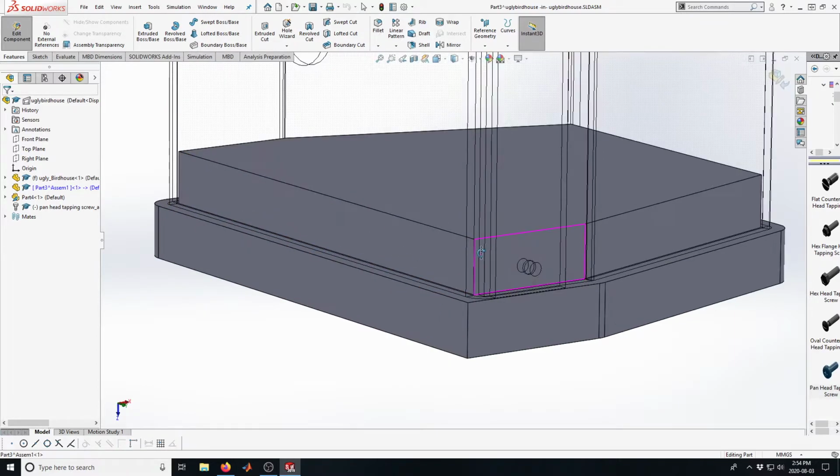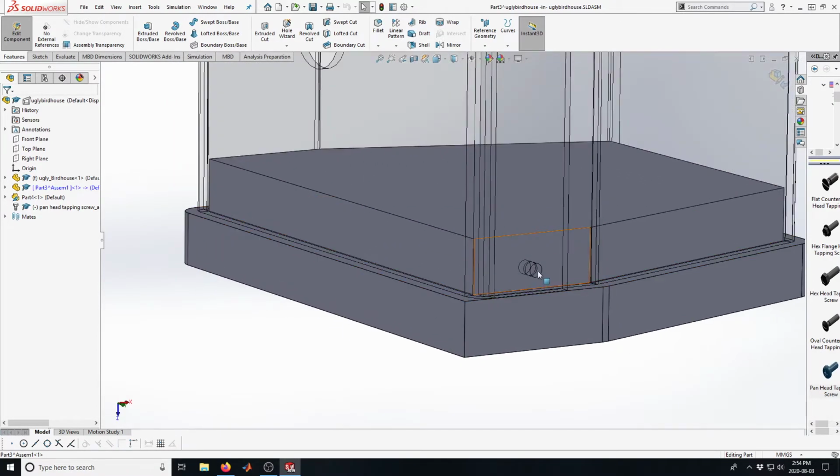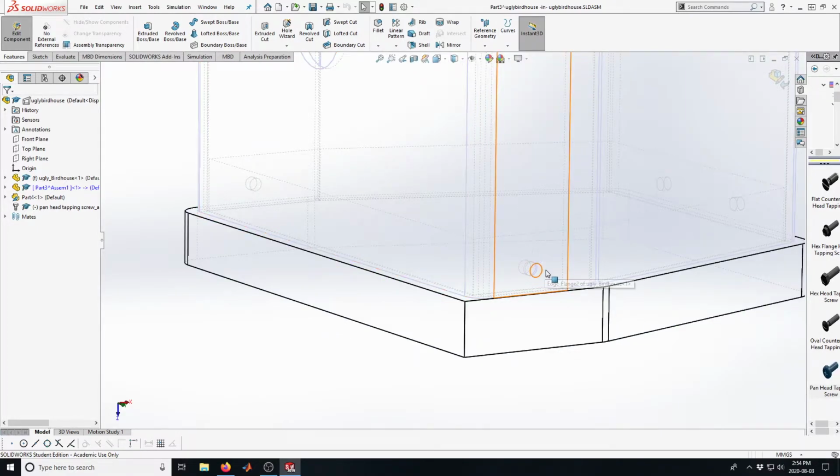So what I want to do is use those holes, and the reason I can't select them is because in this view, because I've made that guy transparent, it misses picking those holes. I'm just going to use a different display option there. You'll notice that that's one of the weird, quirky features.